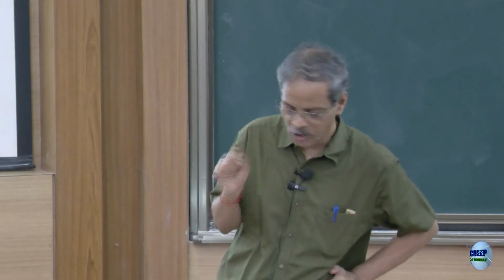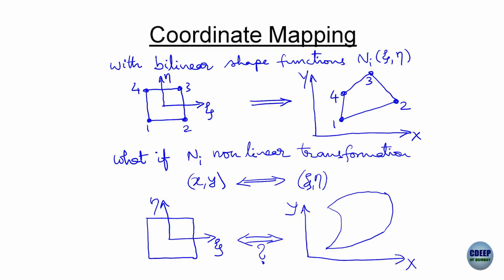Okay. So now going back to this particular case that we are discussing, what is the kind of transformation I should do so that the real world problem is there, it is real, that I need to be able to model curved geometries, and we said natural coordinates gives us that tool to develop that. So we are trying to now see xy to zeta eta, can it become a nonlinear transformation so that my computations will remain easy, double integrals will be evaluated between -1 and 1 over a perfect square domain, but the real physical world distorted element could be modeled.